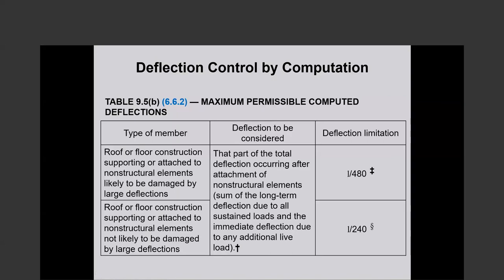What will be the allowable crack width? ACI does not go into allowable crack width. No, we give you the maximum spacing of extreme tension reinforcement. There used to be things said about the allowable crack width, but then we discontinued that. ACI 318 does not go into that.